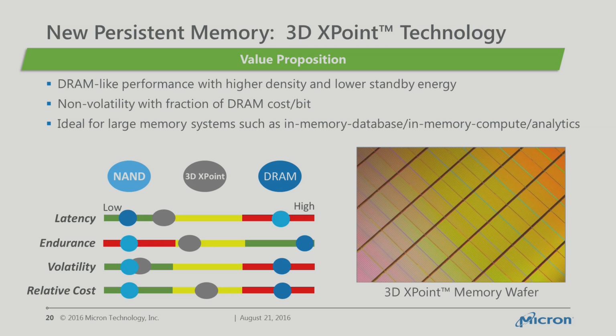which is actually quite important, and that is getting enough data close to the processors. If you can just fill the thing with DRAM, now just look at the refresh power of having that many bits. Right? So the 3D crosspoint energy per transaction is higher than DRAM, but the standby is vastly lower. It's really literally just a leakage standby. And so once you get to, let's say, about a terabyte of memory, now your overall energy is lower with 3D crosspoint because you're not refreshing it. So a lot of interesting scenarios there.